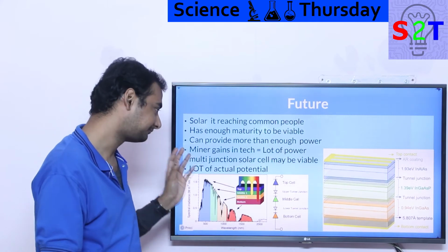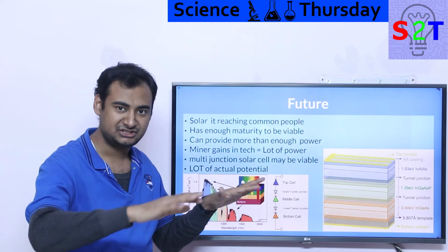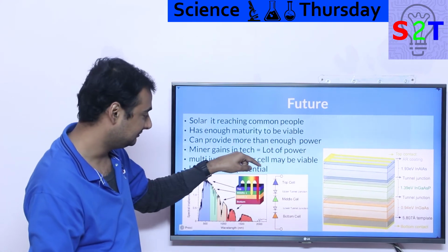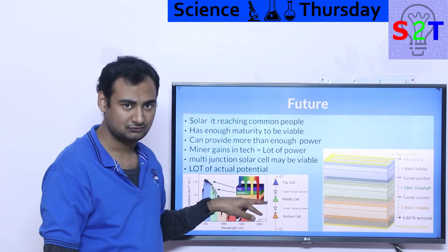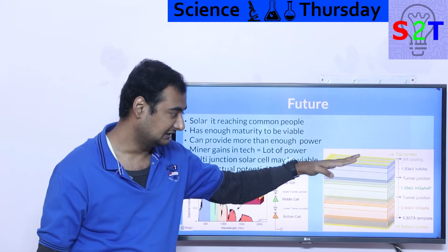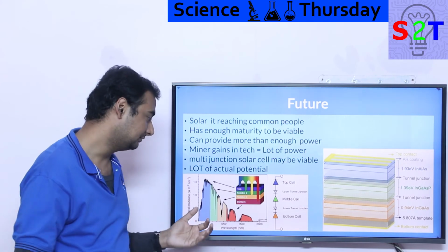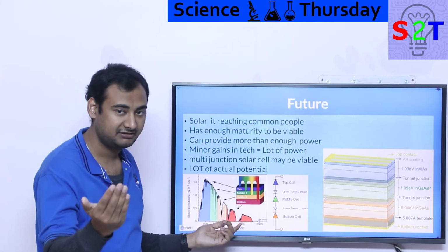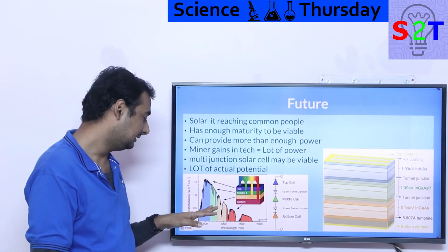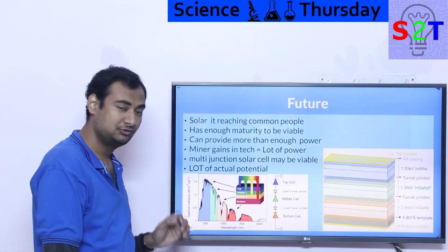That is amazing. And how about the next level? We got the solar cell, it's matured, it's mass produced. What's the next big thing? The next big thing is the multi-junction system. Basically you will have multiple diode architecture, and again two back-to-back diodes to make what we call a tunnel junction, so electrons do not flow backwards, and each layer, each junction, will be fine-tuned for one spectrum, so to say. So you can take a scenario where infrared to red will be taken care of by one junction, then the yellow spectrum by another junction, the green spectrum by another junction, the blue spectrum by another junction.